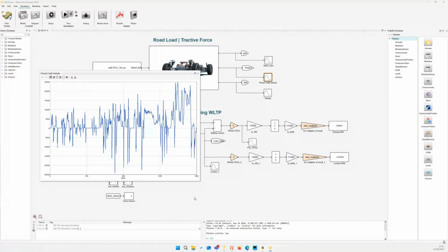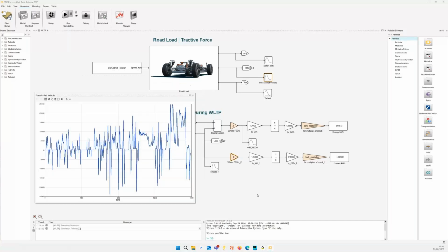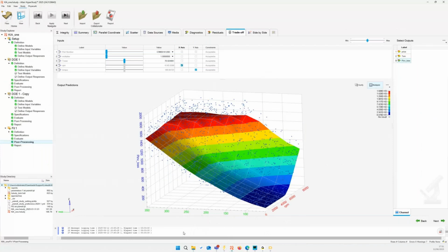I don't want to call them tricks, but we want to be smart here. We don't want to have, for example, switching simulations when you have a drive cycle. Instead, we used PSIM to generate all of these working points. So all of these blue dots are working points that PSIM reached in, let's say, a total of 20 or 30 minutes of simulation running in parallel to steady state.